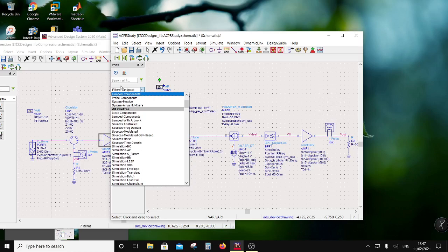Now see how many cycles will fit in a baseband which is a few kilohertz. For microseconds you have to do simulations, with a sample of nanoseconds. So in time domain, this is going to take a long time.